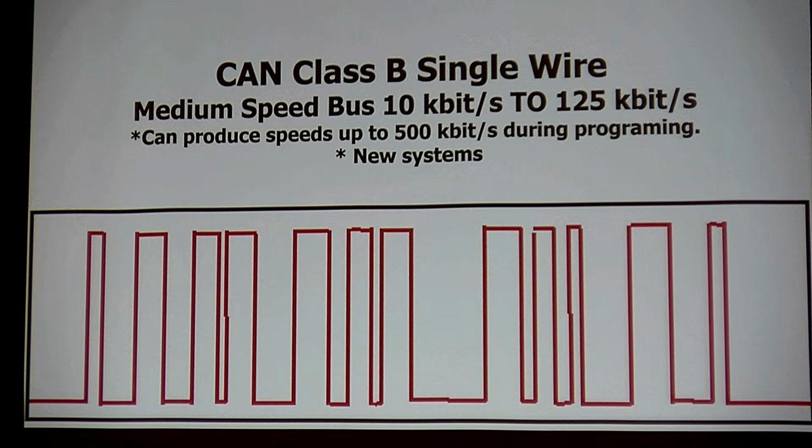Once I arbitrate, I can speed the bus up, and I'm not looking to see if one is there compared to another one. I'm not comparing. All I'm doing is banging the bus, right? I'm just sending bits out. So I can make the bits go way faster, and I can increase my data from having 8 bytes, 64 bits, and I can go up to 64 bytes now with flexible data. And that's something that can be run on the exact same system. I didn't have to change any of the physical layer. The computer's the same. This is all done in the software that this can all happen. So this is pretty cool stuff. Now I have really fast transmissions to where I don't bog things down, and it's just another way.